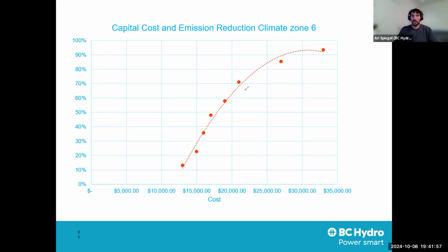So maybe a week, maybe 2 weeks. And the rest of the time, it's operating at sort of more reasonable -5 condition. So there is a balance point. I think -5, province-wide, is a really good balance point in terms of where to size heat pumps, just because we do have so much heating at that temperature and above, and then below we start to see that drop off. And you're just not utilizing all this capacity you paid for as you get into colder and colder upsizing.